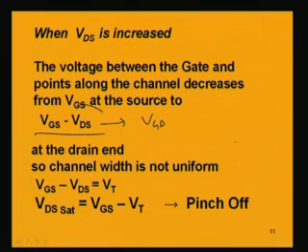And at that point the saturation of the drain to source current occurs. That means the increment of VDS, if it is such that VGS minus VDS finally becomes equal to the threshold voltage, that is called the pinch off point or the saturation point.